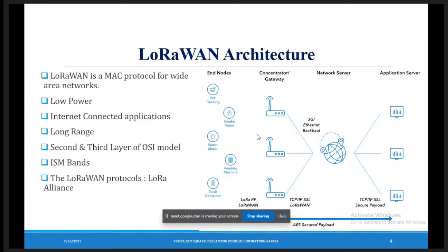With the help of the microcontroller, I convert those electrical data into a readable data format. After that, with the help of the LoRaWAN or LoRa chipset, I convert those data into a radio packet. After converting those data into a radio packet, it will emit the radio packet in a particular channel. Channel means frequency channel. I'm talking about a frequency channel, for example, 865402500. It's one set of a frequency channel.